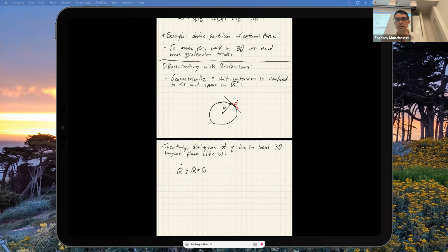where that's the quaternion product and this hat thing means to stick the 3D omega vector in as the vector part of the quaternion. And then we also talked about all this weird notation that I made up, where we define a left multiply, capital Q. So we define this left multiplication matrix-like operator, that's equivalent to that quaternion product. And then we also define this hat matrix operator that takes a 3D omega, and basically it's a row of zeros and then an identity block. So this guy maps us into this guy, and this L of Q is equivalent to left multiplication by the quaternion. So this encodes the quaternion multiplication as a matrix. This is convenient because now I can just use normal matrix math to differentiate this and so on. That's why we do that.